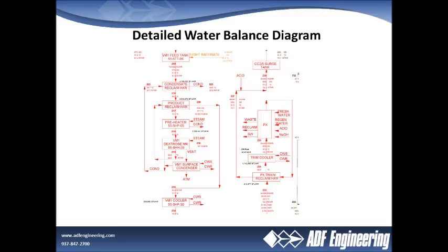And it has a mass balance with your temperature, the quality of the incoming water, the quality or the constituents in the water going out, and then quantified data for each stream. So each inlet and outlet is quantified. This is a fairly involved exercise, but it's a very important exercise so that we enter into the water reuse program with a complete picture of what your facility has.